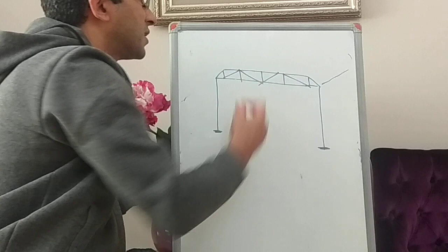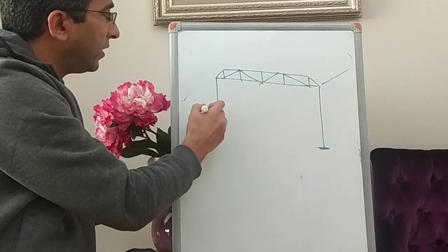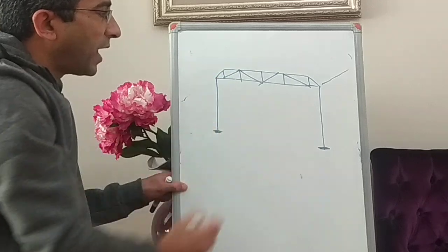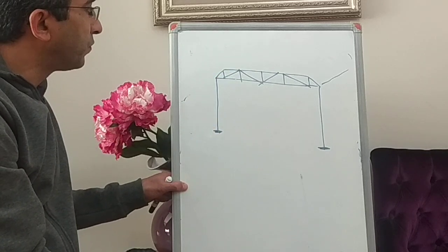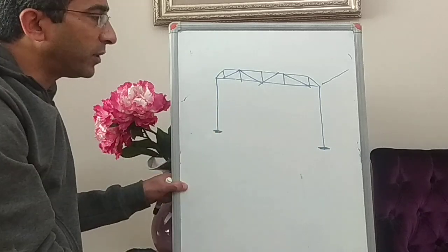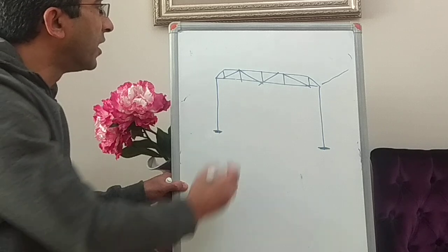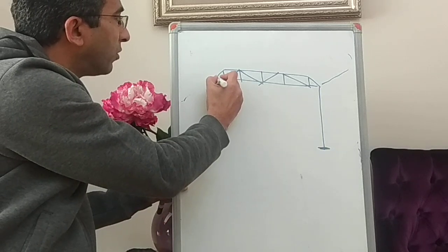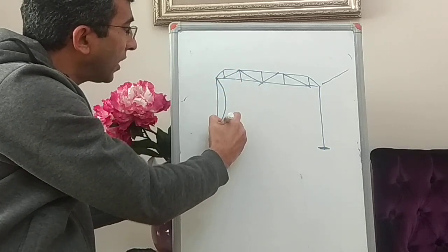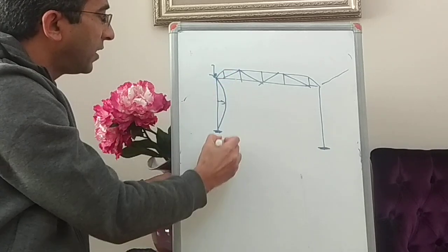Of course this repeats itself. This is the factory. Because these columns are long and cylindrical, they may have what we call a buckling problem or instability problem. Before material failure, this column may have lateral buckling under the effect of loads.